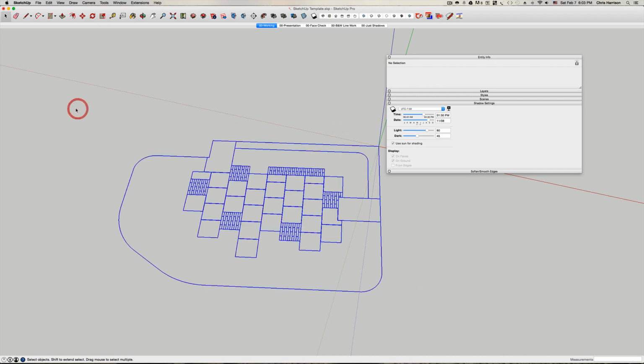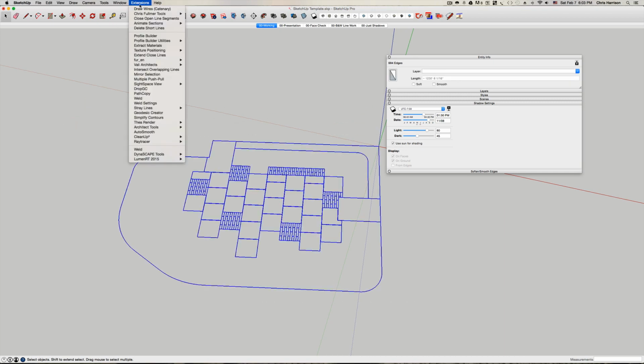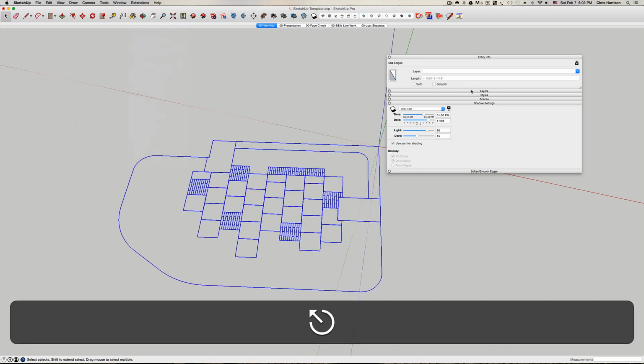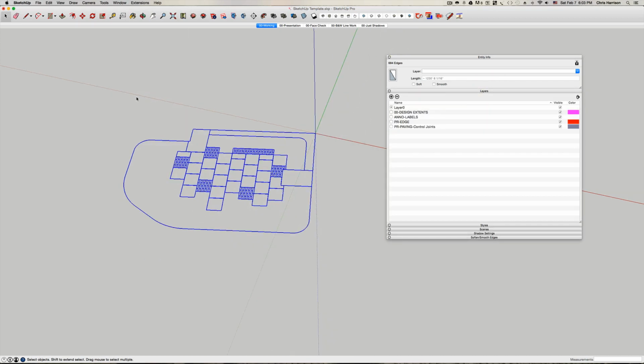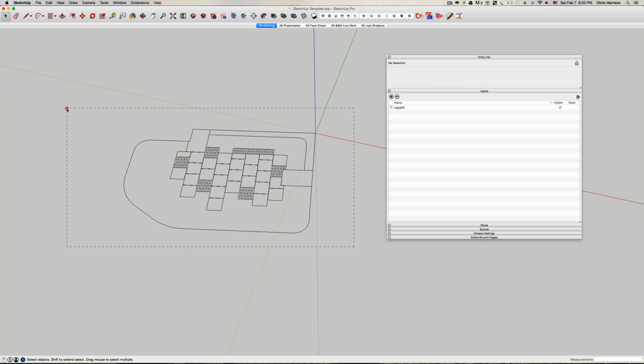So I'm going to select this information and the line work, and I'm on layer 0. Let me show you that. First of all, I'm going to try to clean this up a little bit. I want all this line work basically to be on layer 0. I don't need any of this stuff right now. So I'm going to select everything by holding shift and hit delete and say move to current layer, and I'm on layer 0. So now everything is just on layer 0.